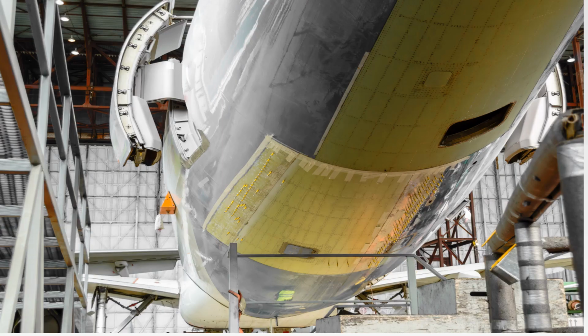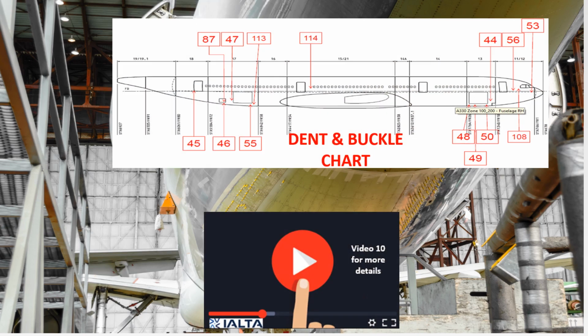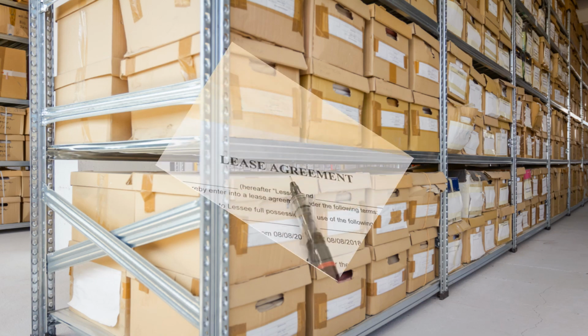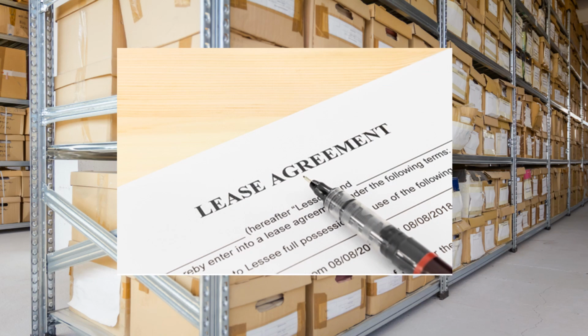The sheet metal and structure work on an aircraft has a lot of associated technical records that contain the damage location, the SRM or structural repair manual references, the damage classification, dent and buckle entries, and repair files. As highlighted in video 2, the airline must also retain a hard copy of the paperwork, and this will be returned in the boxes when it comes back off lease to be reviewed by the lessor, to ensure that the airline has met the technical return conditions outlined in the aircraft lease agreement.